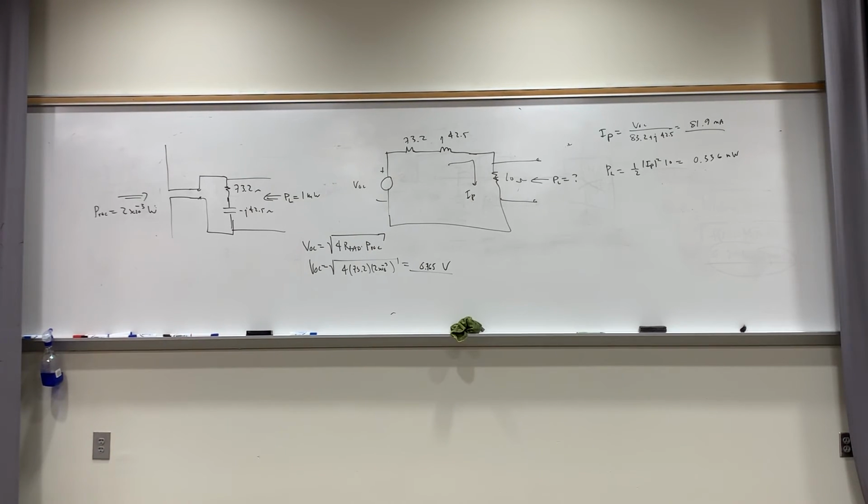And you have to be aware short dipole and half-wave dipole have different equations. I'll tell you what, I'll give you the equation for the electric field for a half-wave dipole, but I'm not going to give it to you for a short one. You're going to have to know that one, all right? In fairness, I think you should be able to handle that. For a short dipole, it's j eta beta I L e to the minus j beta r sine theta over 4 pi r. I think you can get that one.